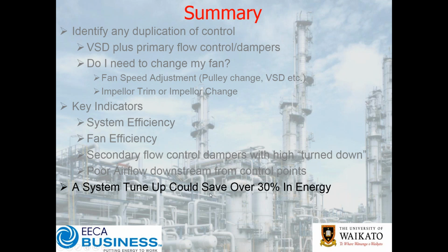I know it's a bit cliche to talk about these sorts of numbers, but if you're sitting there today thinking, well, what's in it for me? Is there something I should be looking at? Well, have a look at what you're spending on all your fans and run the numbers and say, look, if I can get 20-30% off that, what's that worth to me? That gives you a ballpark figure straight away as to whether it's worth looking at.